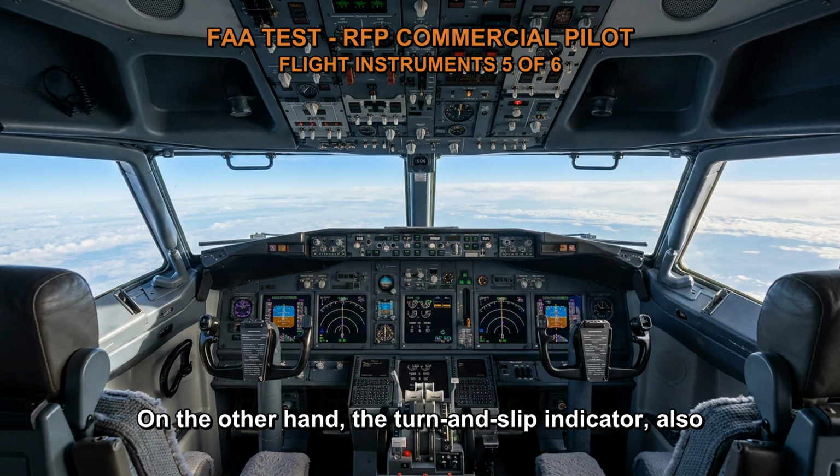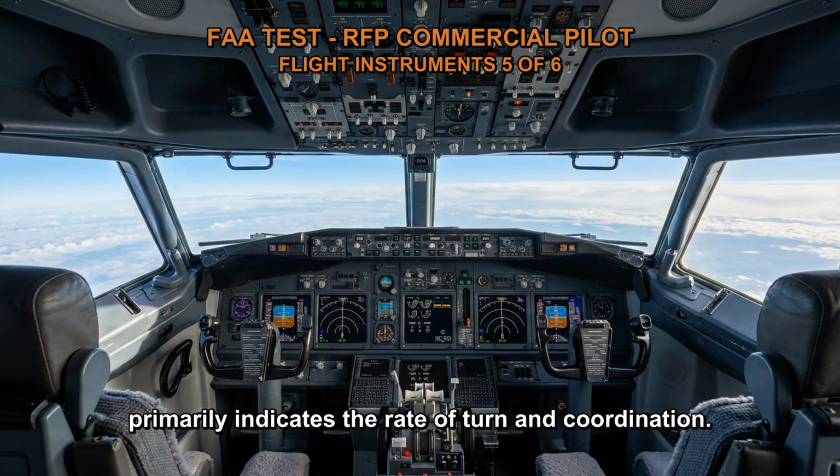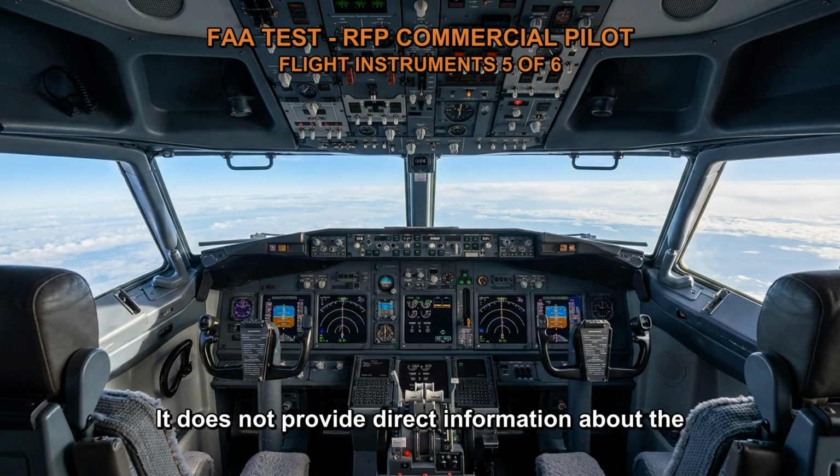On the other hand, the turn and slip indicator, also known as the inclinometer or the needle and ball indicator, primarily indicates the rate of turn and coordination. It uses a needle or a ball to show the rate of turn and the coordination of the aircraft. It does not provide direct information about the roll rate of the aircraft.